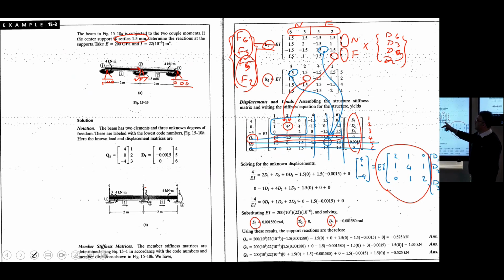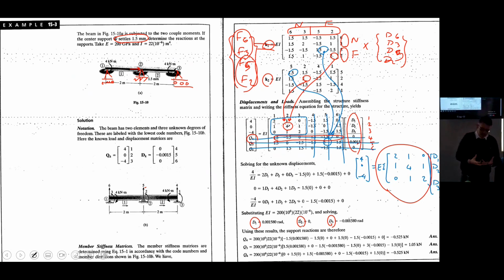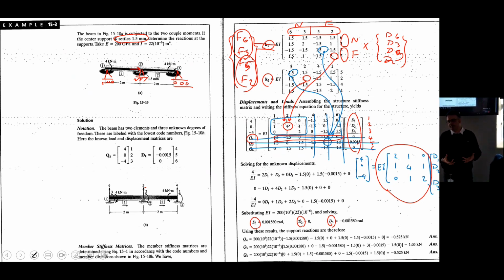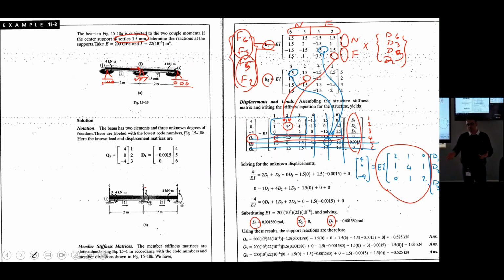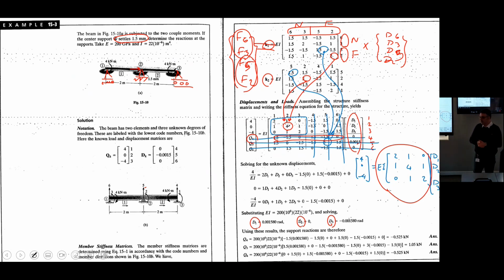So when you have settlement, we had settlement in some previous examples, didn't we? It means that we have a support, but it's in the middle of the river. Water washes out the soil beneath it, and over time it just settles a little bit down. So for these kinds of structures, this effect can cause some internal forces.